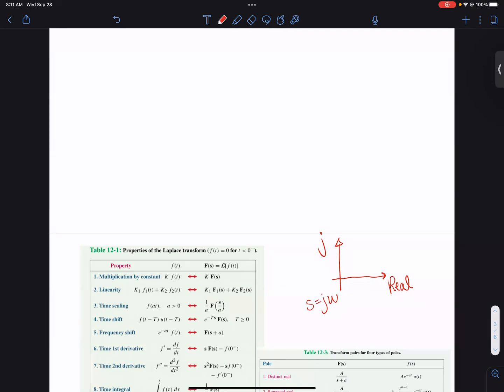Yes, the complex plane is a great way to think about this. Think about the S domain as your complex domain. Student: I'm still a little confused about the main difference between the complex domain and the frequency domain. Is it just that relationship S equals J omega? Yep, S is the same as frequency, it's just that the J is in there. So it's just on the imaginary axis, the value of your magnitude there. All right, thank you. Hopefully that helps.